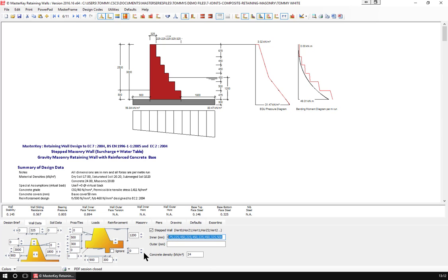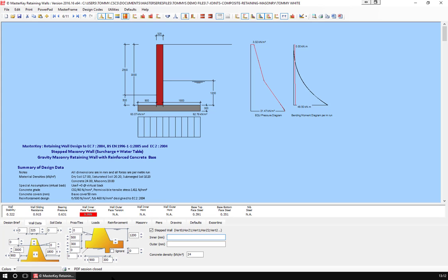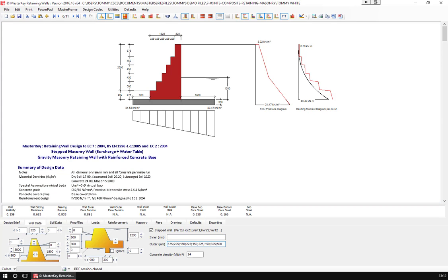So if I wanted to, I could take that out. We're back to plain and it's failing miserably, and I could even put that on the inner side. So if you were propping up where you'd excavate it under somebody else's property, you might want to go for this arrangement instead. Again, I don't like them, but sometimes needs be. They're more useful when you're doing a simple 1.5 meter high wall, but for this 2.5 meter high wall, your solution is most